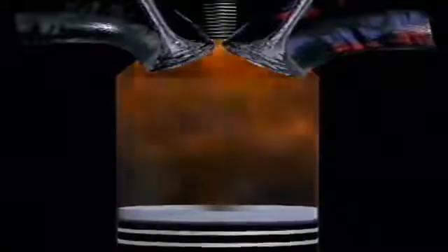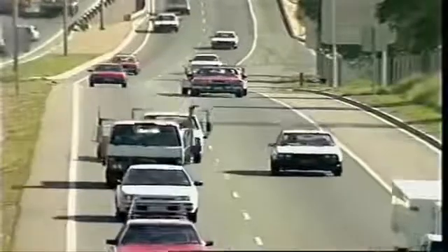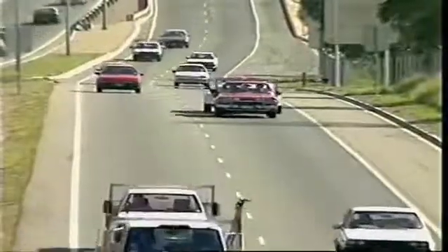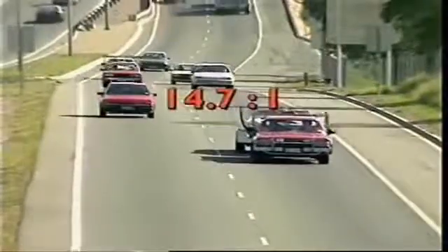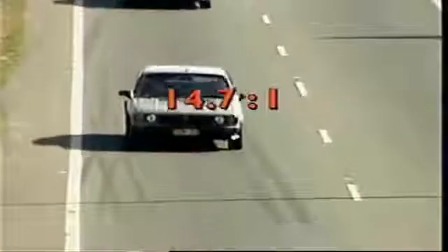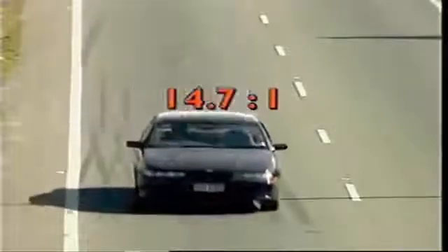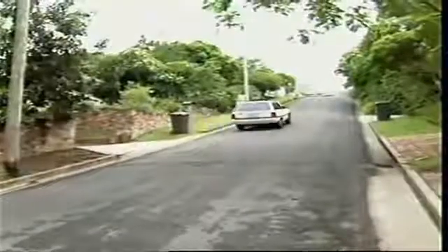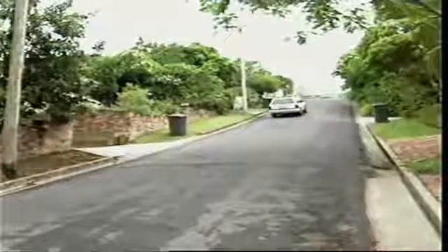Exactly how much energy is required varies according to the condition of the mixture and the pressure in the cylinder at the end of the compression stroke. With an engine at normal operating temperature and under a light load, a mixture with a ratio close to the ideal of 14.7 to 1 ignites readily. However, suddenly depressing the accelerator to increase speed or to maintain speed when hill climbing causes cylinder pressures to rise. This increases the firing voltage needed.